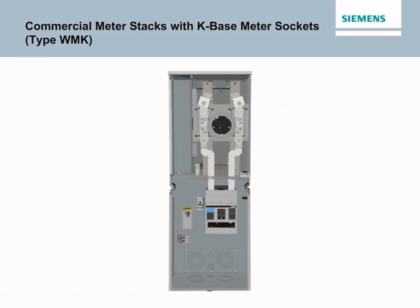K-Base is a bolt-in meter socket design and provided exclusively by Landis & Gyr. Utility acceptance varies, so check for approval prior to selection. Commercial meter stacks with K-Base meter sockets, type WMK, are available with 240 volt max, single phase, 3-phase tenant main provisions. 3-phase in, single phase out stacks use the K5 meter socket. 3-phase in, 3-phase out stacks use the K7 meter socket. Both types of sockets are available in 1 position, 400 and 600 amp configurations. K7 modules are also available with 2 positions at 400 amps per position.